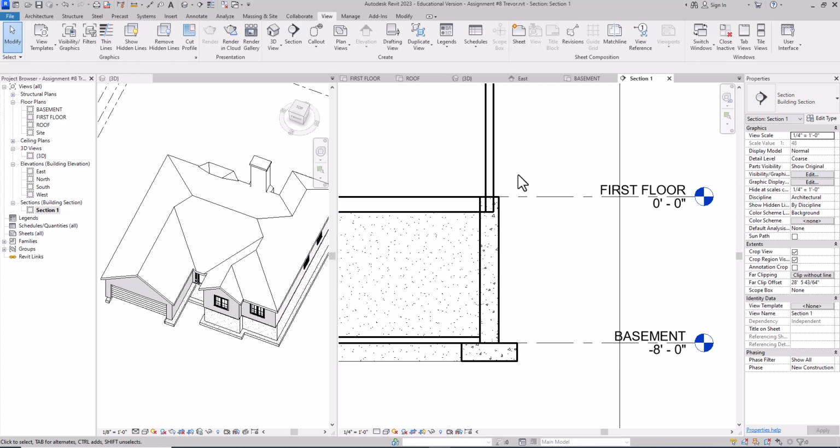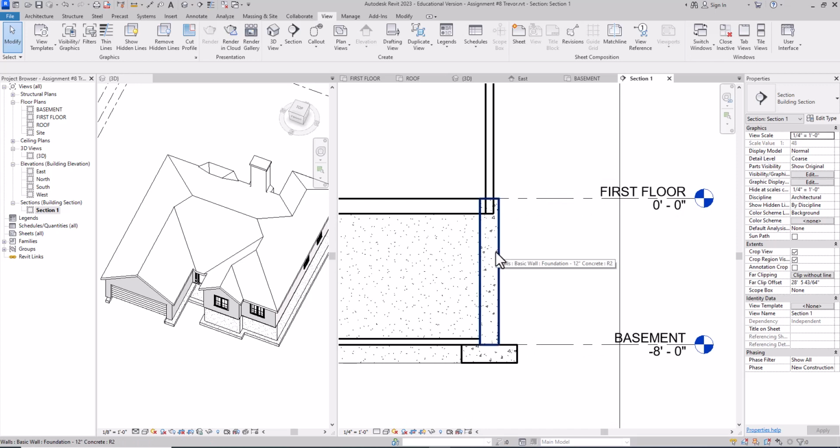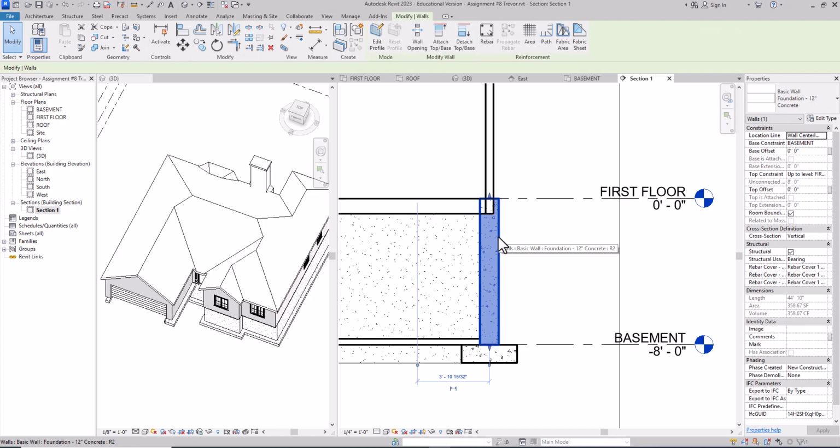So in this design drawing, we're not picking up the actual details of it, but if we were working with construction drawings, and it's siding, we'd make sure that when we drew this foundation wall, it would be in line with this outside wall. One thing you could do, because this would be like the floor joists, is you don't need to here, but you can change the top offset to whatever your floor depth is. So now we're talking about construction and not design.